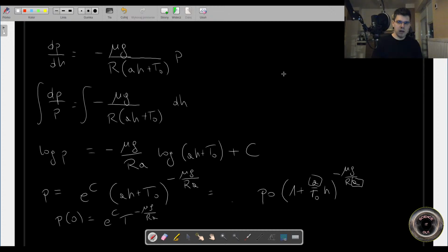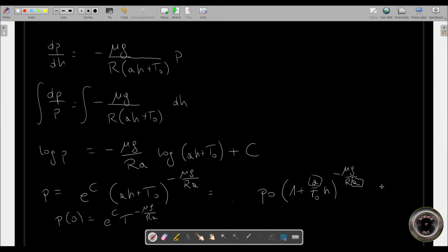So then basically if we have, let me turn off the camera again because it's eating up precious real estate on the screen. So if we have some interval of altitudes here, where temperature behaves in a linear fashion, and we know pressure somewhere in this interval, for example for this altitude, we can calculate from this equation pressure both at this end and at this end and along this whole interval.